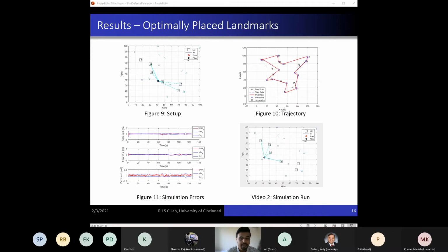This set of figures highlights the result for the optimal route and associated landmark points. Results highlighting the importance of joint optimization, instead of having potentially non-optimal solutions, are discussed in the thesis as well as in the respective papers. We are given 15 waypoints to travel through and an associated landmark placement point. In figure 10, we see that using the joint optimization, we find the optimal waypoint sequence and associated 8 landmark locations that can keep the system observable.